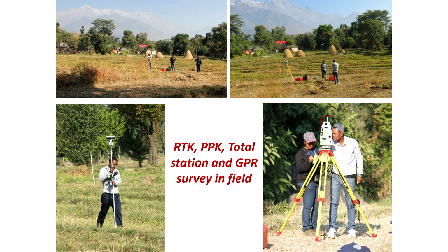So, where we can put the receiver on the top, that is your GPS antenna on the top, and that can also work seamlessly, and the person can move with the prism as well as the other receiver. Okay. So, that one can do. Further, even if you do not have the total station, then you can do the mapping in real time kinematic mode. Okay. And you can even do post processing kinematic, or the integrated total station.